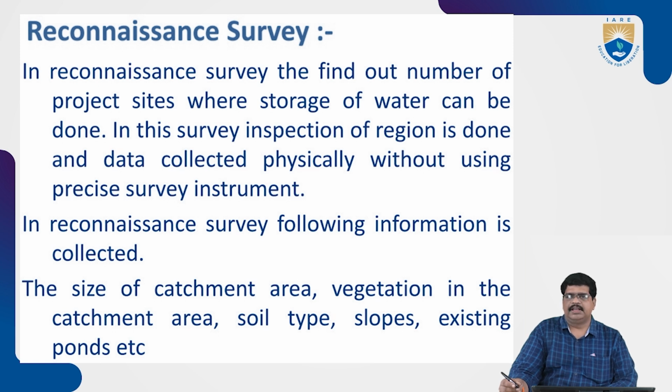Next, primarily soil type. Which soil is it, whether A type, B type, C type or D type? The classification was given previously for calculation of runoff. Each soil has one curve number, and the runoff can be calculated using the SCS-CN curve number method. Based on the curve number, the infiltration capacity and the storage capacity can be known using the soil investigation and soil types.